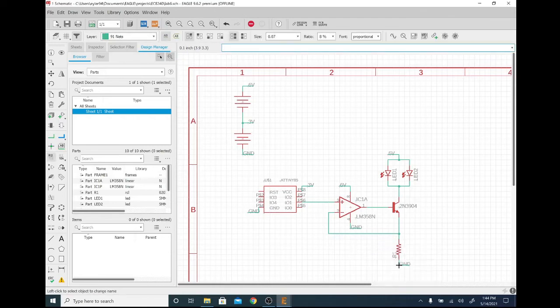All right, now all of the tracing is done. The last thing I need to do is determine the value of resistor here. So if I have 3 volts at this point, because those are going to match each other when that's high, and I want 20 milliamps flowing through each one of these LEDs, that would be 20 milliamps plus 20 milliamps is 40 milliamps.